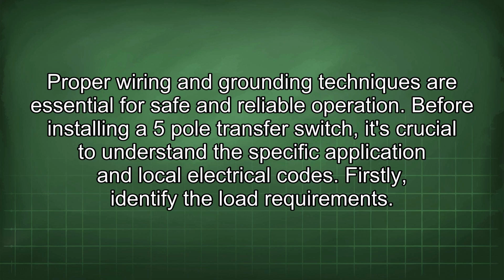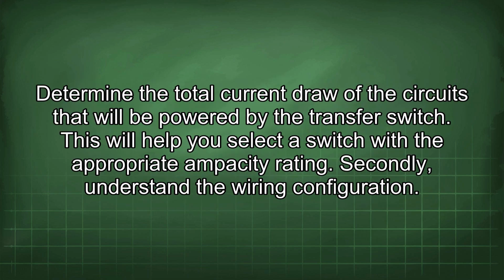Before installing a 5-pole transfer switch, it's crucial to understand the specific application and local electrical codes. Firstly, identify the load requirements. Determine the total current draw of the circuits that will be powered by the transfer switch. This will help you select a switch with the appropriate ampacity rating.